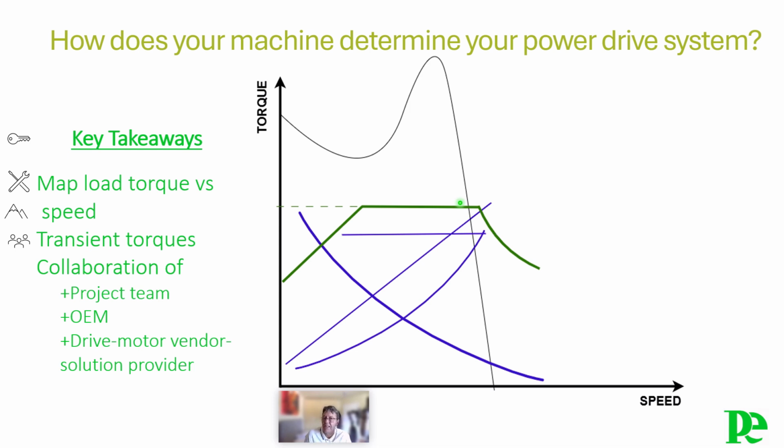Okay, this relates still to the steady state operation, but in many applications the drive combination must also deliver short transient torques, often surpassing the rated motor torque. For example, consider a large loaded conveyor belt in the cement industry where up to 180% of rated torque can be required just to start it up. This is often called the breakaway torque.